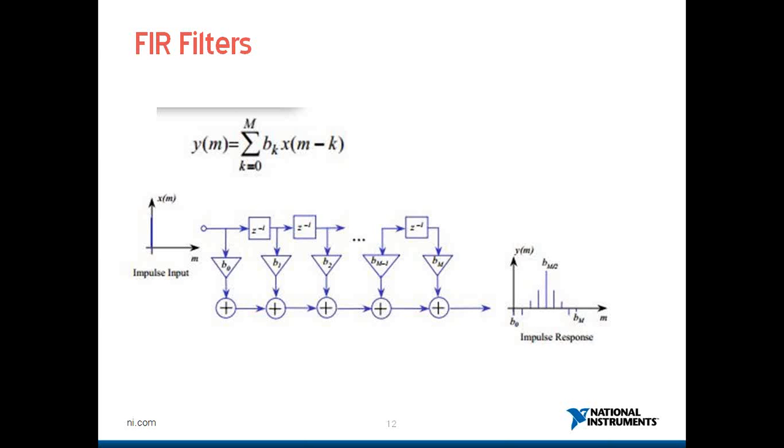Now if I take a transform of the same, what I'm going to get is a transfer function with a numerator. So the numerator defines the zeros and the denominator defines the poles. Now because I don't have the poles in this case, it will be a more stable response as compared to a transfer function with both numerator and denominator, which you're going to see ahead in IIR.